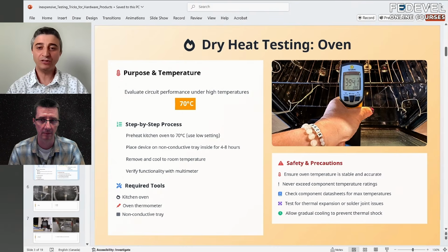You use a thermometer, you use a temperature sensor like an NTC, and measure everything on your board and go gradually. This way, it will expose any weakness in your design or any issue in your engineering that was not done right. This is the time to find it. If a heat sink was not properly designed and fitted for your application, this is the time to find it, rather than shipping it out for an outdoor application and having to deal with it after the fact. Finding this issue right away is really easy.